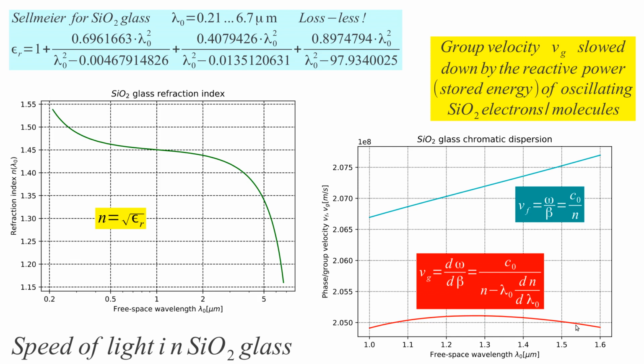This curve is really about 2 times 10 to the 8 power meters per second. It seems quite a flat curve. It doesn't seem much of a problem. But the real problem of the waveguide, the optical fiber, is that we have very long fibers. A fiber may be 100 kilometers long. 100 kilometers is 10 to the 11th power of micrometers, and the wavelength in glass is about 1 micrometer. So this transmission path is actually 10 to the 11th power wavelengths long.